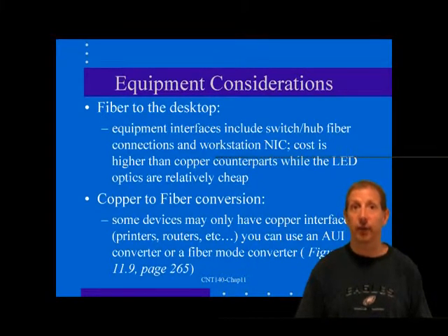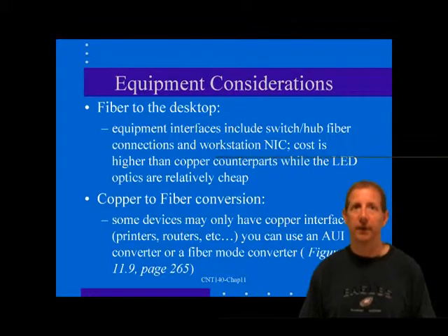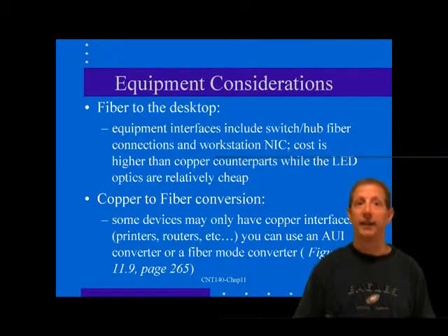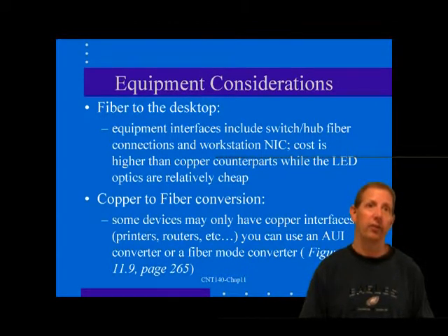the price of the copper interface to drop considerably, even though the innovative VCSEL laser diodes that are used with gigabit Ethernet fiber are much cheaper than the older technology that they still represent, and they still represent a significant cost penalty over copper transceivers.